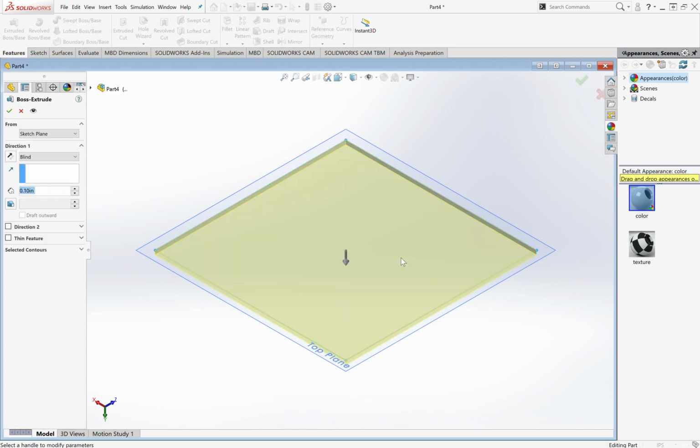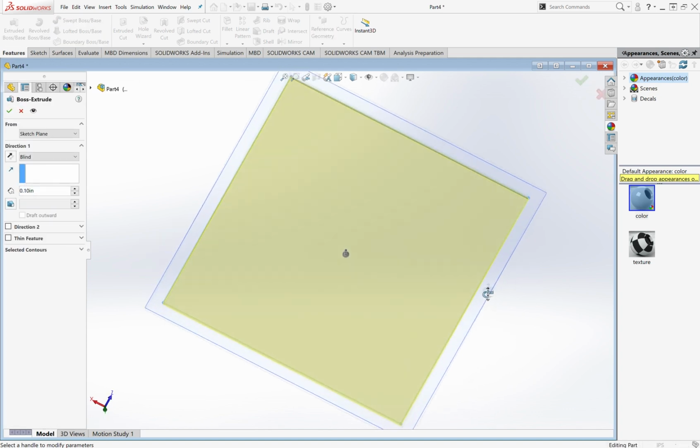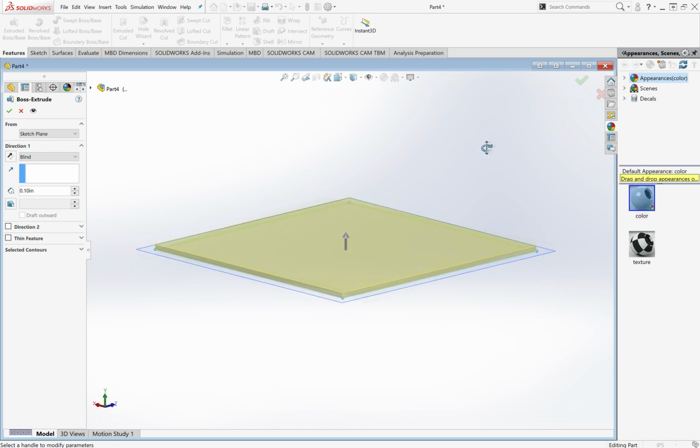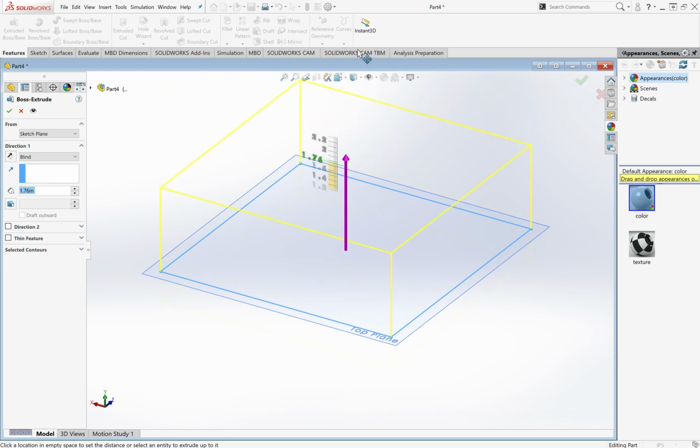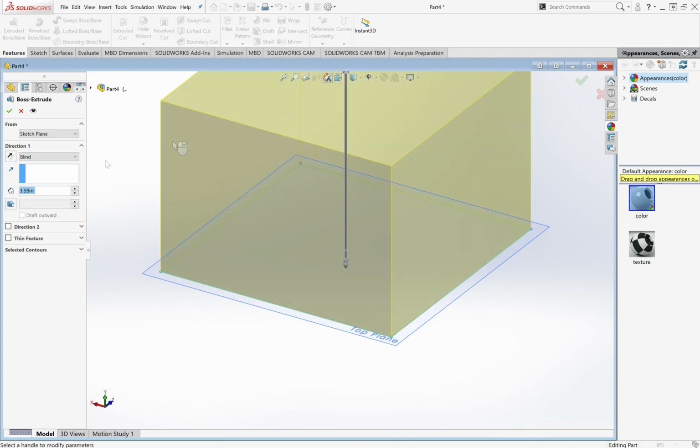All right, perfect. I'm going to rotate us around because I messed with the views. All right, we see this arrow here. Now I could just select this and drag up and make it how big, or I can make it come from the other side of the top plane and drag down. But let's make it a perfect cube, 5 inches over here on the left.